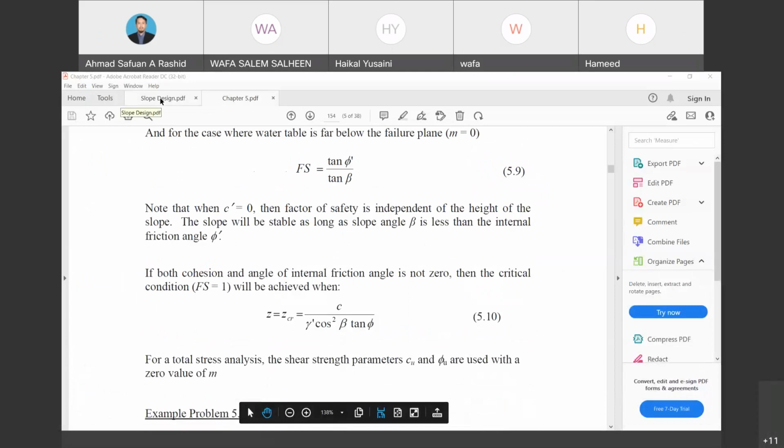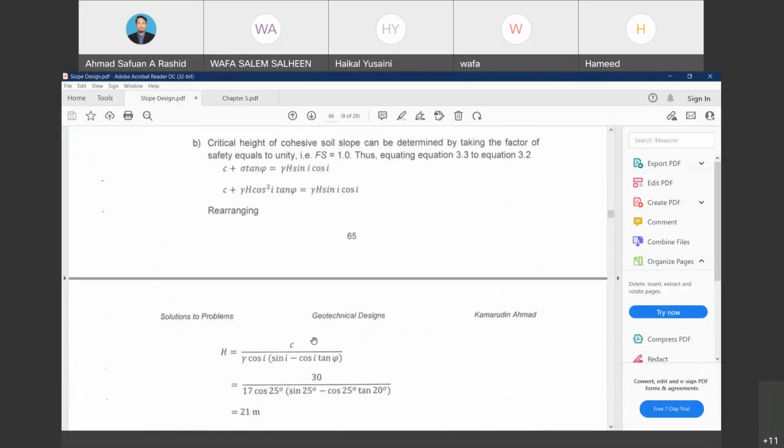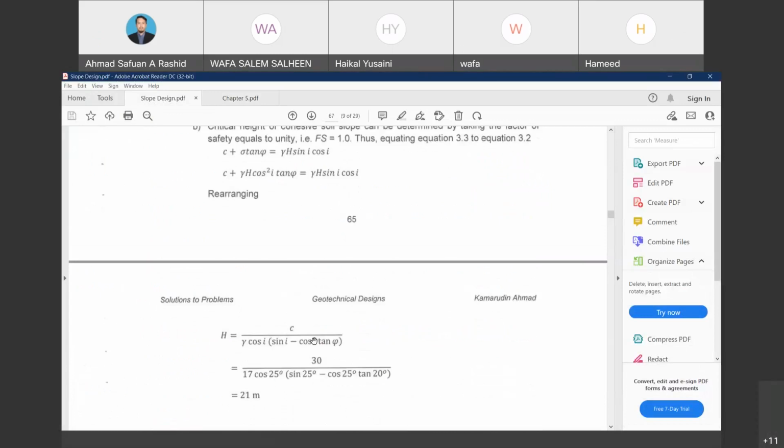So for me, it's better not to rely on the simplified equation. It's better for us to use the raw equation from S and tau and then get the effective safety. That is much easier, and we also may understand better.